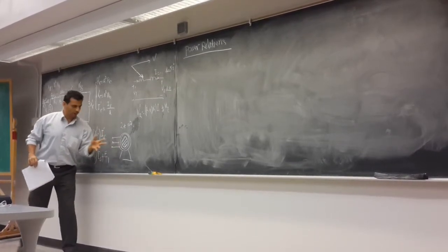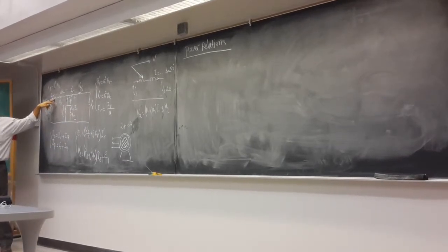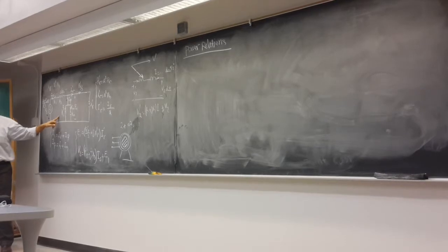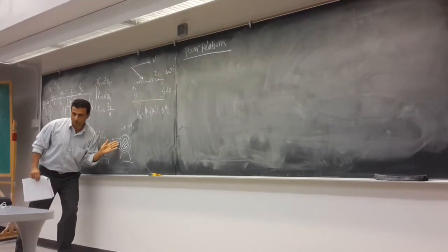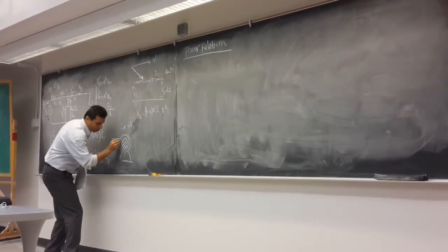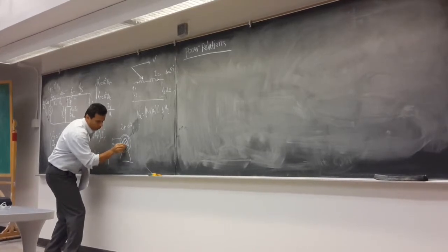In a stator, what do we have? We have a copper loss, right? And what else do we have in the stator? Core loss, right? We say the core loss is in the stator. So basically, the power comes to the stator, and we are going to have copper loss and core loss here. After that, this power is going to go through the air gap to the rotor.